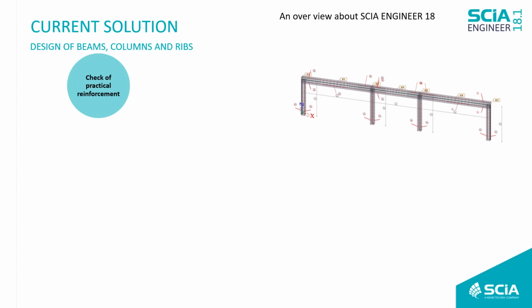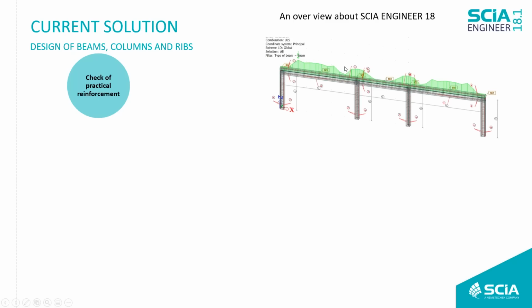Again, I will explain the main workflow, the first one. As a concrete designer, I have a long experience. I can decide from the beginning the amount of the reinforcement. When I see just the internal forces, I can a little bit predict what the final reinforcement will look like. And in that case, I can use this workflow by modeling all the reinforcement inside my beams or my columns. And then to be sure, I will ask SCIA Engineer to check if that amount of reinforcement is okay or not. So this is the main workflow.